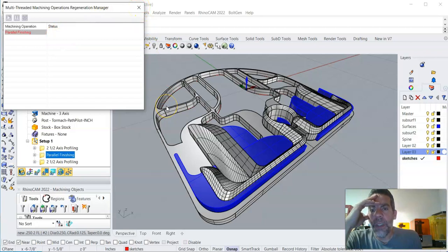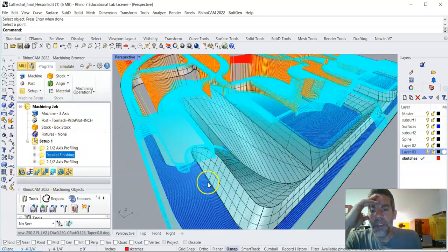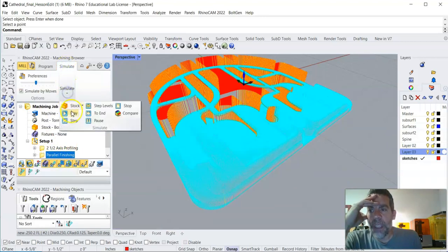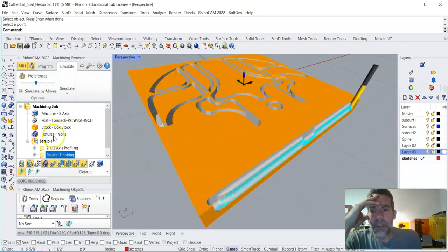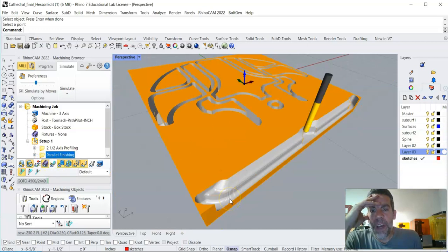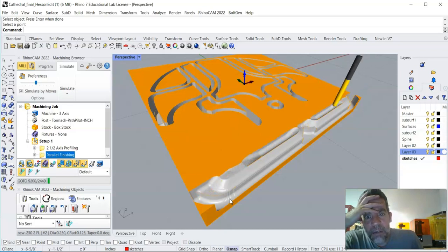So we'll let this finish up, and you'll see it will be more lines if we turn on the toolpath, and you can see there's way more resolution essentially in those lines. So let's play that now so you can see what that looks like, and we'll turn off our tool path. So you can see you're getting a much finer finish because it's barely stepping over, and you're just using the tip of that larger bit, which again was probably contrary to what you might think.